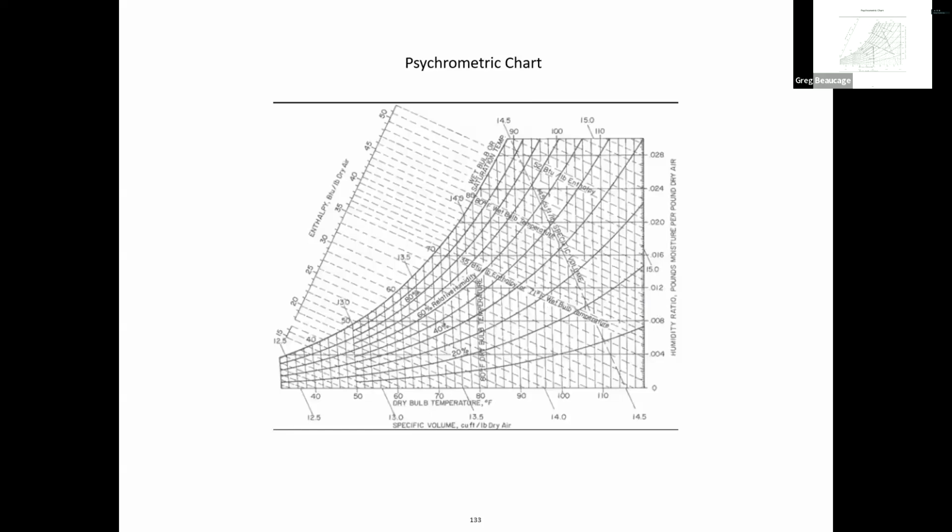So it's when it's totally evaporated the water. The drier the air, the lower the wet bulb temperature relative to the dry bulb temperature, which is just the thermometer on the table. Right. So if you can get the wet bulb temperature and your dry bulb temperature, and the wet bulb's going to go along the isenthalpic or the adiabatic line to your dry bulb, then these lines would give you the relative humidity of the air. And then if you go over here, that gives you the percent water, the weight of water in the air versus the weight of the air.